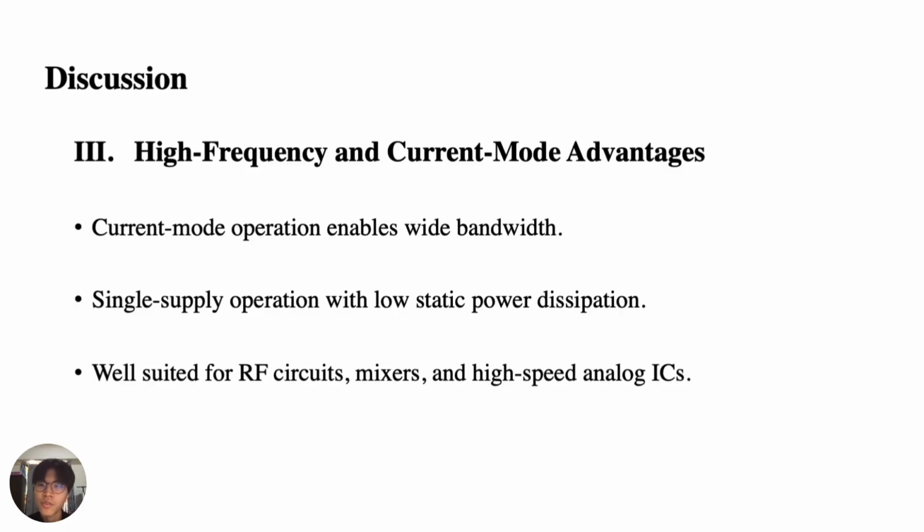Finally, from an application perspective, the circuit operates in the current domain, enabling high bandwidth and wide dynamic range with a single supply voltage. These characteristics make it well suited for RF front-end circuits, mixers, and high-speed analog integrated circuits.